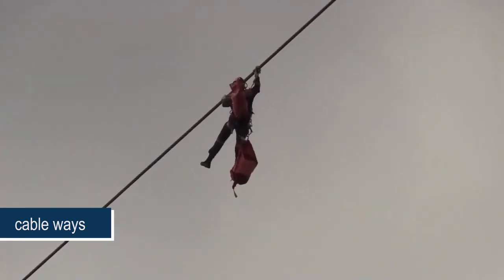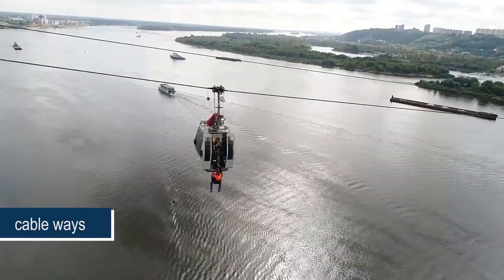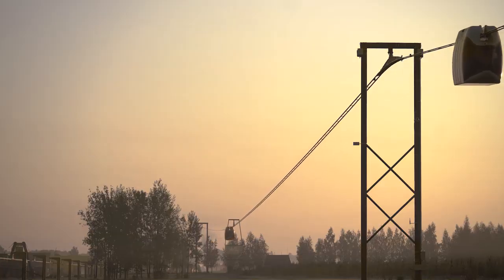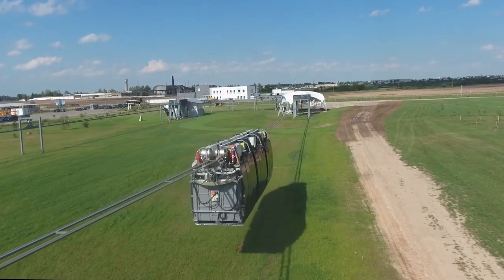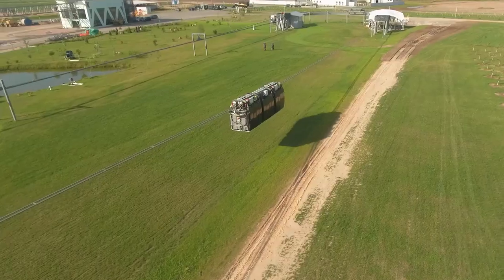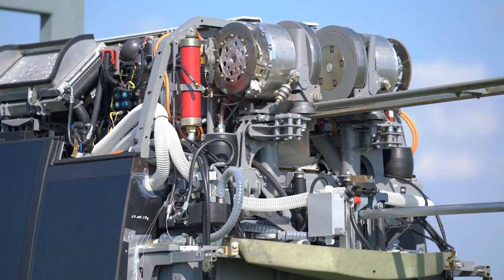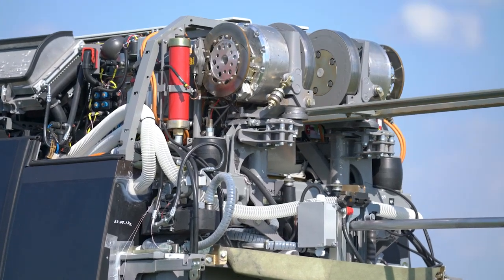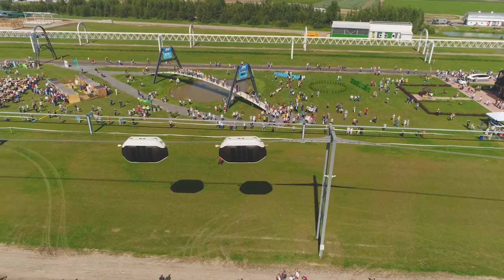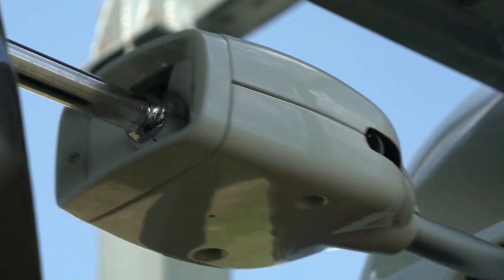Unlike cableways, where stopping the system leads to complex and costly measures to evacuate passengers, the possibility of emergency stopping of the Unitsky string technologies vehicle in the middle of the route is actually excluded. Emergency batteries are provided in the rolling stock in case of a power supply failure. Each wheel is driving, so failure of one of the wheels will not stop the system. If this occurs, the vehicle moving behind will tow the other car to the nearest station.